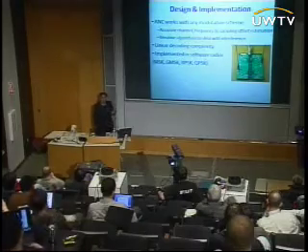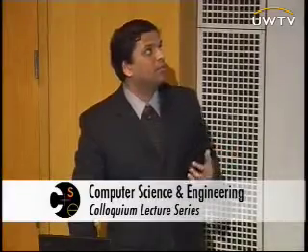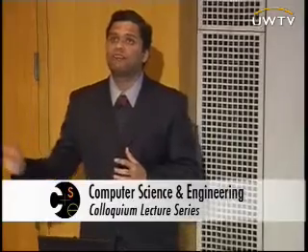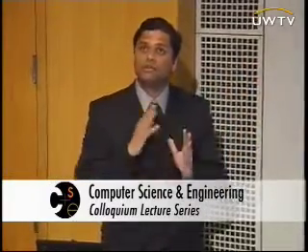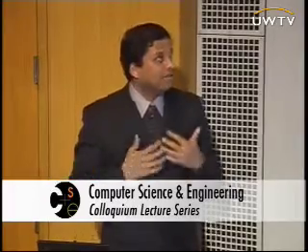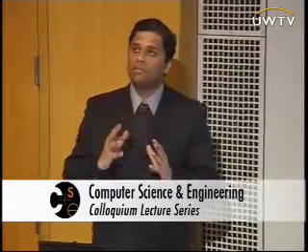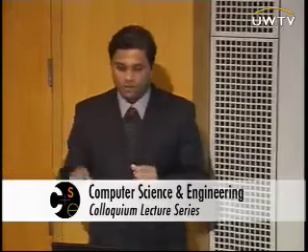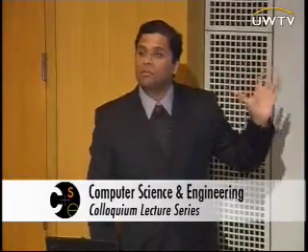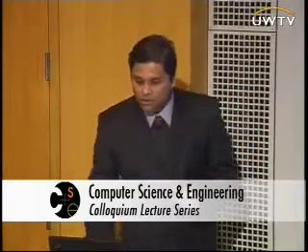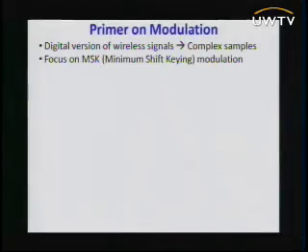So before I get into the decoding algorithm, let me give a quick primer on modulation and demodulation of wireless signals. As in any digital communication system, you can represent a real signal using samples. And just trust me on this, wireless signals can be represented using complex samples. Since I'm going to focus on MSK, which stands for minimum shift keying modulation scheme, the way MSK signals bits is by angles between consecutive complex numbers it transmits on the wireless channel.